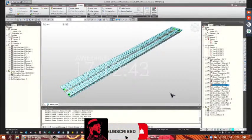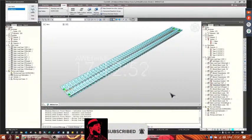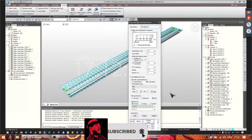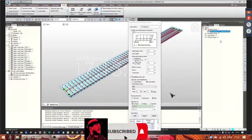The traffic effect has been modeled with the moving load optimization function. It's a traffic lane for this model. The moving load optimization function automatically finds the most onerous disposition of the lanes in the transversal direction. In this project, we have a 4 meter and 0.5 carriageway. And in this model, we use the cross-beam distribution of vehicles, since we create a structural group that is made of beams, of these transversal elements.